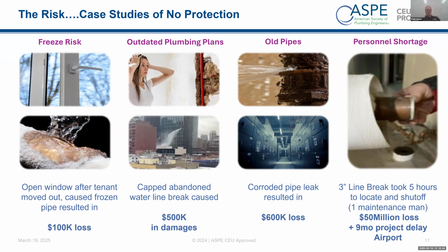But of course, if you get leaking pipes down into switch gear, you guys spend a lot of money on that switch gear, $500,000, $5 million on switch gear. You want to protect it. You want to either not route your pipes over the switch gear, which is the smartest thing to do. Some guys, what I've seen them actually do is if there are pipes routed over it, they'll put dams around it. So if it leaks, the water comes down and goes around that switch gear, at least doesn't go straight into the upper vent holes of the switch gear.